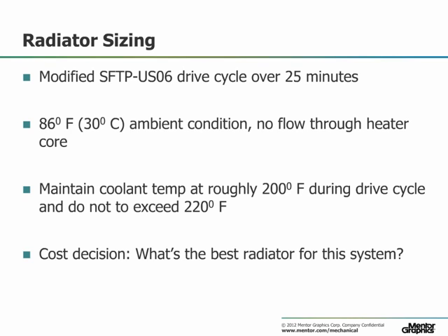The ambient temperature is 86 degrees Fahrenheit, assume a closed heater valve, and the goal is to find a radiator such that the system maintains a fluid temperature of roughly 200 degrees Fahrenheit without exceeding 220 degrees Fahrenheit.